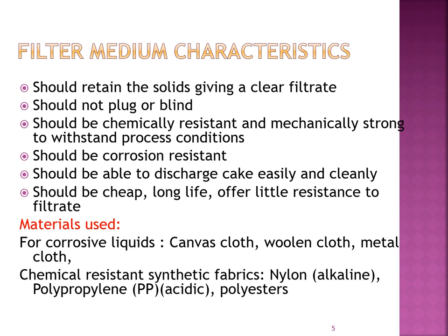What are the materials that can be used as a filter medium? For corrosive liquids, we can use canvas cloth, woolen cloth or metal cloth. But for normal day-to-day applications, we can go for polymers like nylon, polypropylene for acidic condition, and also polyesters.